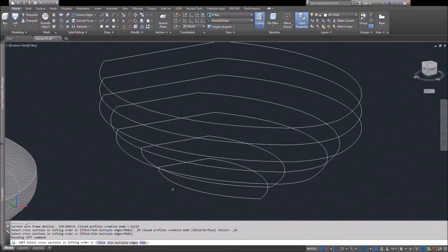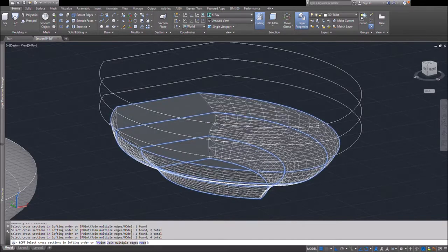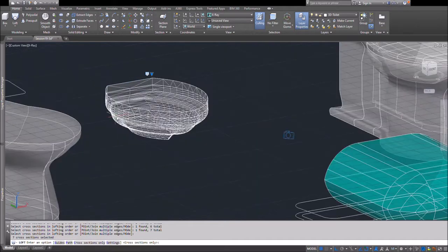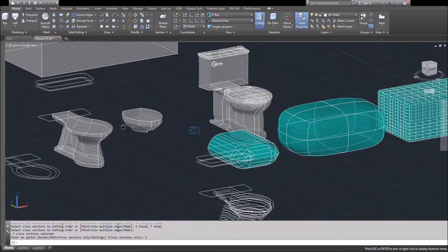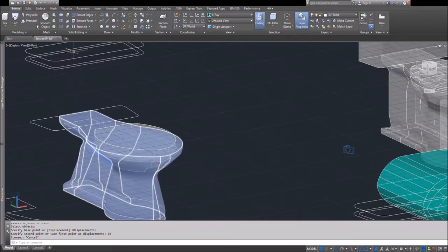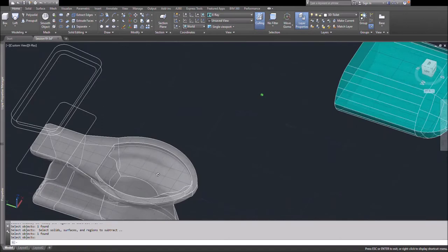That way, when I'm done with it, I can move it back, right? Very easily and very accurately. So here I am modeling or lofting out the profiles of the interior of the bowl. Actually, this is the negative space, right? This is the hollow of the bowl. So I will move that hollow, that solid that represents the hollow part of the bowl, into that model that defines the bowl itself, because that is modeled as a solid, right? And I'll use my solid subtraction tool and be able to subtract that from the model of the tank.